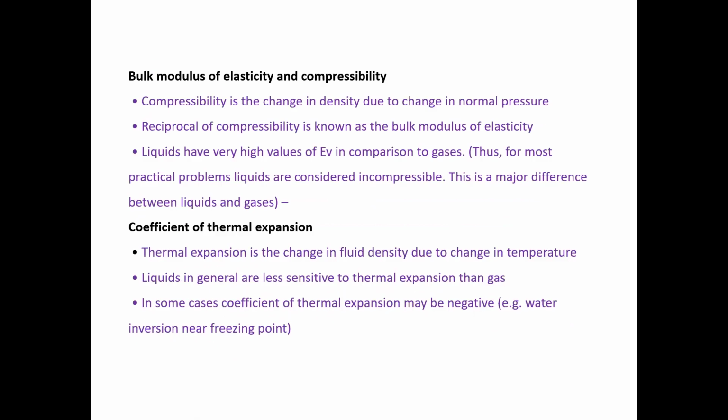And another property is the bulk modulus of elasticity and compressibility. Compressibility is the change in density due to the change in normal pressure. The reciprocal of compressibility is known as the bulk modulus of elasticity. Liquid has a very high value of elasticity as compared to the gases. Okay. Coefficient of thermal expansion. Thermal expansion is the change in fluid density due to the change in temperature. Liquid in general is less sensitive to thermal expansion than the gases.